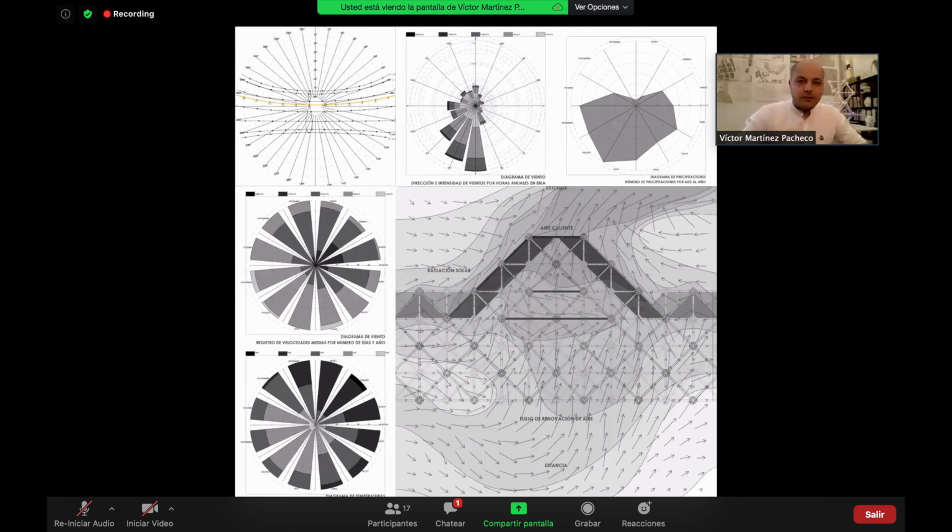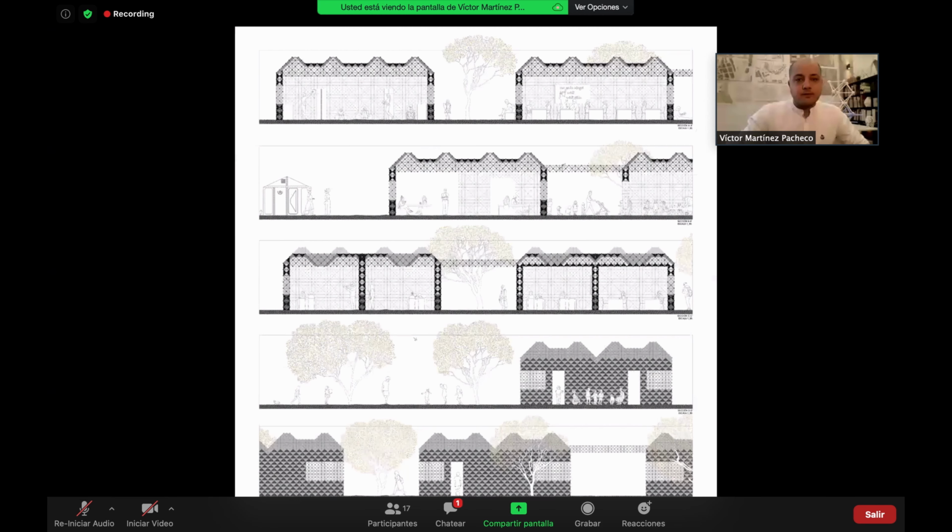And of course, when designing such an architectural and sustainable project, starting from the fact that it doesn't require industrial machinery at all, we started with the design of an air conditioning system by solar chimneys. It works by balancing the temperature through differential pressure in the fluid. The cover form is a consequence of these chimneys.